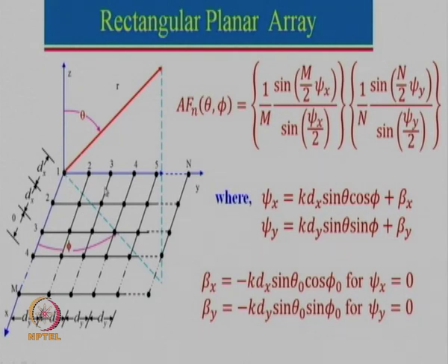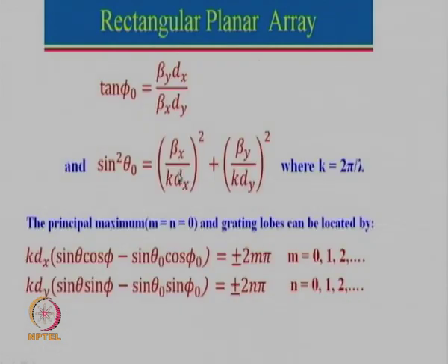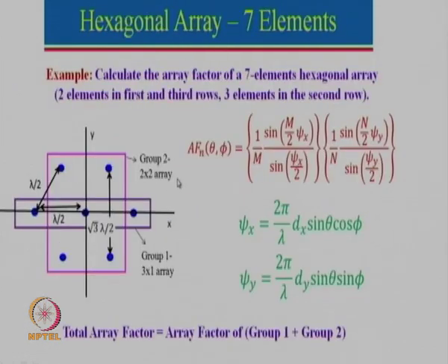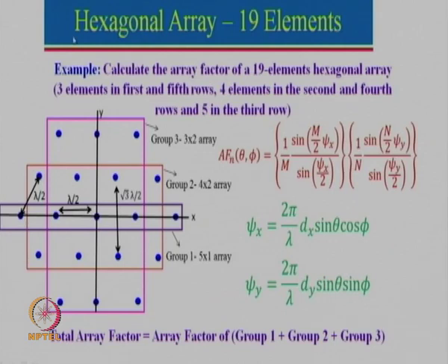and that is where a hexagonal array does help. If you look at a hexagonal array which we just looked at, over here this distance is lambda by 2, or if I take this as d, then this is d. So I can still take this 0.7 and this 0.7, and I do not have that problem at 45 degrees here. So many times hexagonal arrays are preferred, and as I mentioned, I had designed this particular array way back in 85, and I did use a microstrip antenna.